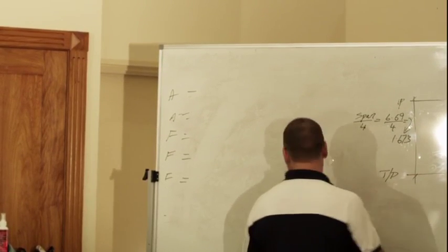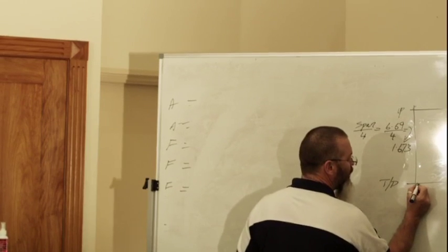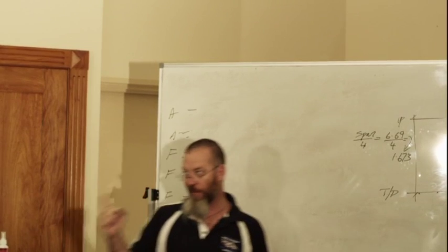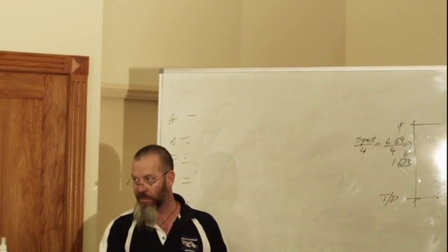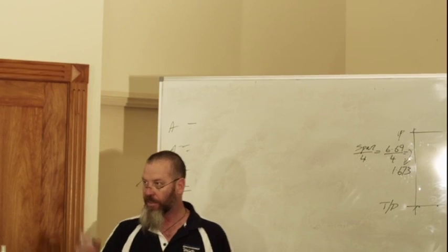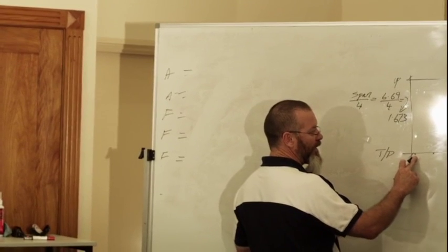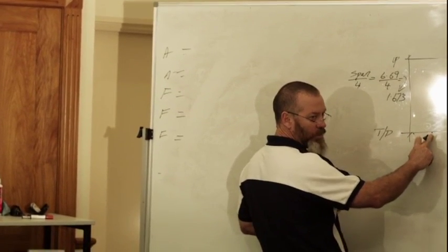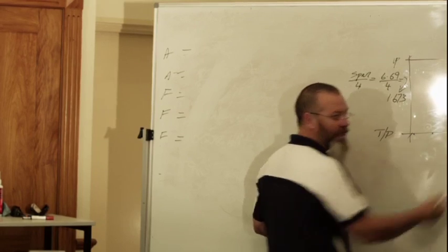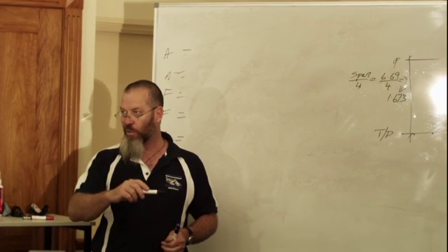Now, upstairs, the rule was that our studs were 600 apart. So I'm going to put my first stud there, my second stud there. Window 5 of the window schedule, which is the one we're doing here, was 1.5 metres apart. So you've got to think about connections. The stud is connected at the plate here. This jam stud is connected at the plate here, and the other jam stud is connected out here at the plate at 1.5. This is where that rule came in before.